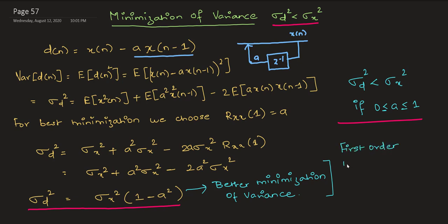So what I'm predicting, right? You may be asking what prediction we are doing. You are predicting two things. Let us say if a is not equal to 1, you're predicting that value of a, and also you're predicting that x of n minus 1. You say that it is a delayed version of x of n, but the predictor block has to supply this x of n minus 1. So it's going to take your x of n, apply the delay using the Z inverse, and then send it back to the quantizer where you can take the difference of x of n and x of n minus 1. So that is your predictor block. Good. We will see more on the predictor block in the coming examples.